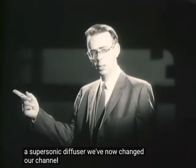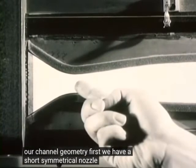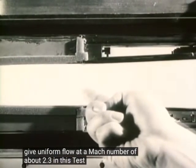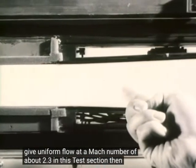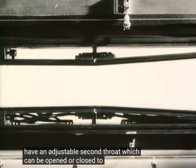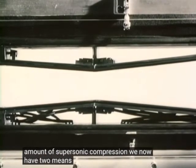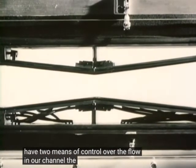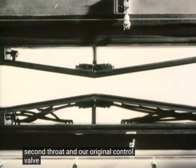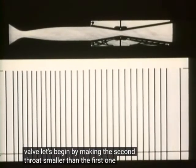We have now changed our channel geometry. First, we have a short symmetrical nozzle designed to give uniform flow at a Mach number of about 2.3 in this test section. Then we have an adjustable second throat, which can be opened or closed to vary the amount of supersonic compression. We now have two means of control over the flow in our channel: the geometry of the second throat and our original control valve. Let's begin by making the second throat smaller than the first one.